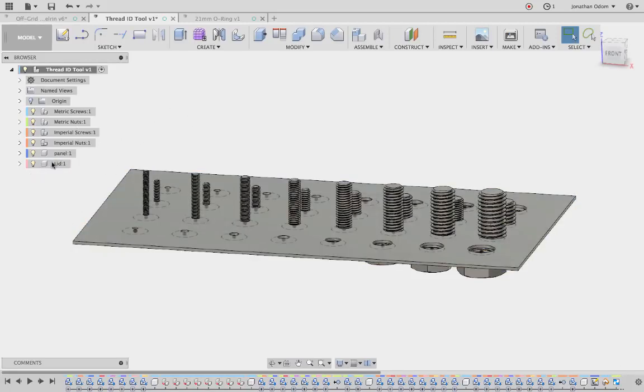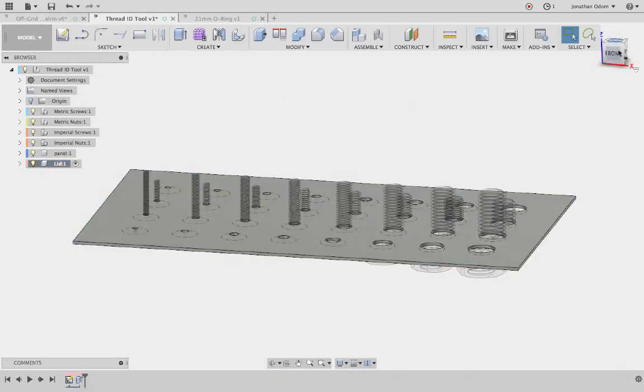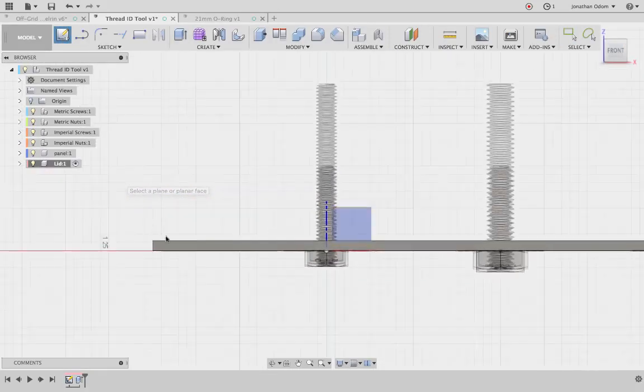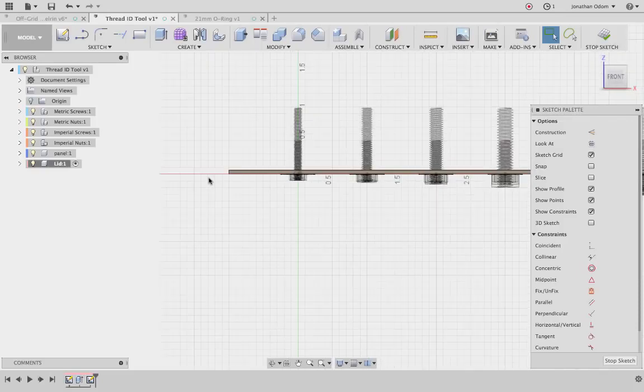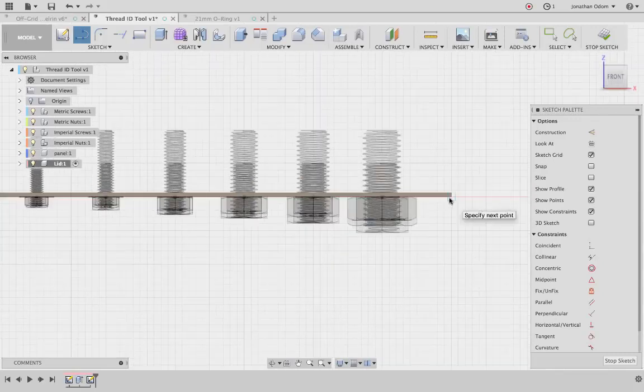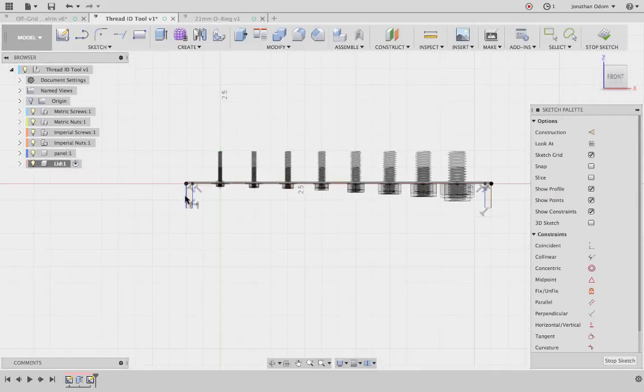Let's start there. Go back to that, activate like this from the side. Then I'm going to do a create sketch on this, and then I'll just draw like a little lip that's going to come down here. Hold shift until I see that little perpendicular thing. You can always add that stuff later, but it's a little bit easier to do it here. All right, I'm going to give those a dimension, so these will be 3 millimeters.